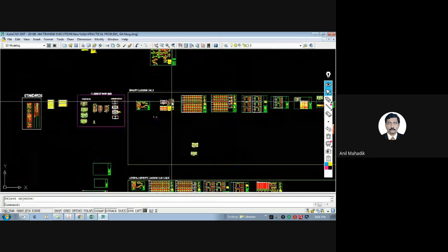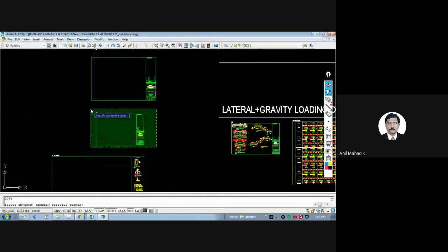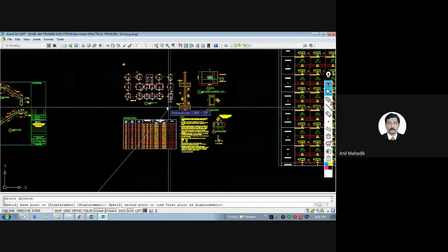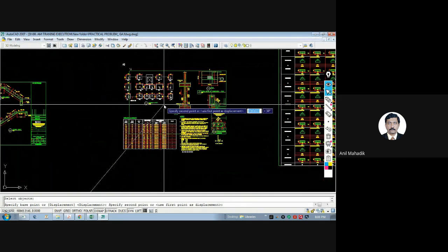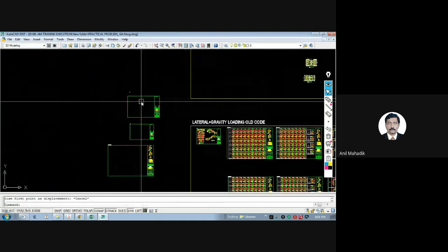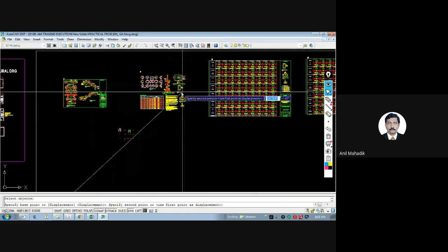Now, once you prepare this drawing, arrange this and just move this object. So let's say I'm copying this A3 size here. And if you take it here near to this, you can understand that it cannot fit in A3. Can you see this? Objects are going out of the page. That means this drawing cannot fit in the A3 size. Now again move the A2 size. Let me move this A2 size and just go there and check whether you can fit it.